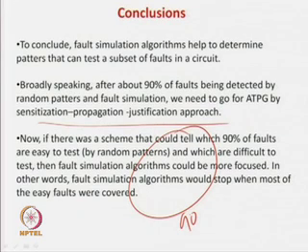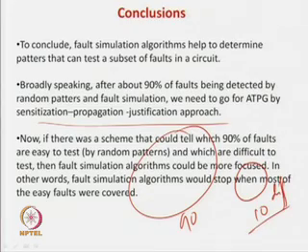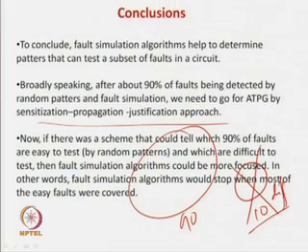are easy to test faults, so apply random patterns for them, and these 10% of the faults are difficult, so do not try for them, that will be very good. At least in the fault simulation we will not touch the 10% difficult faults. We will only touch the 90% easy faults.